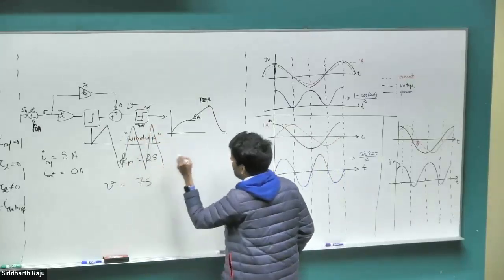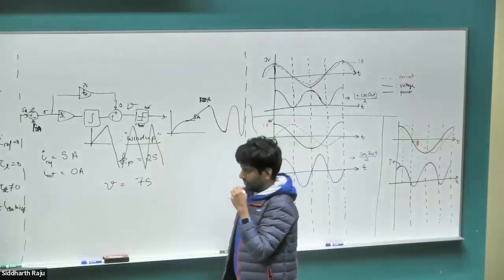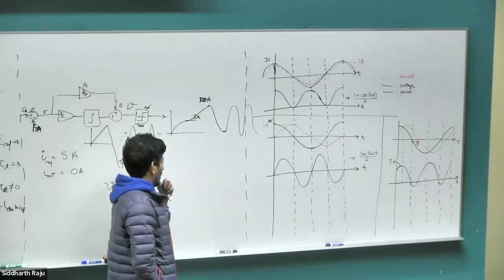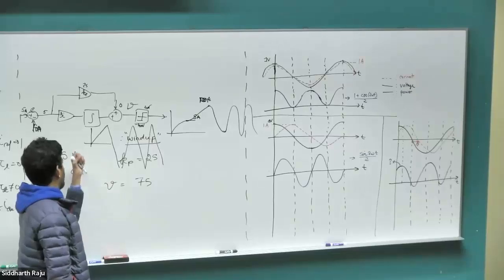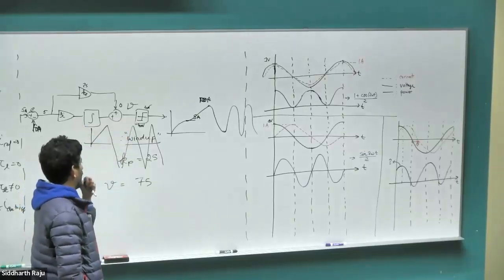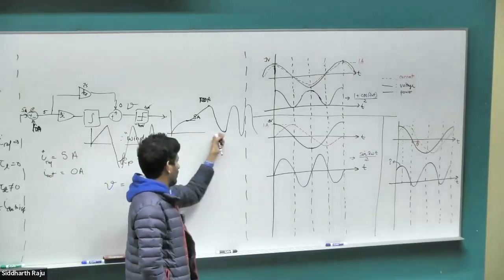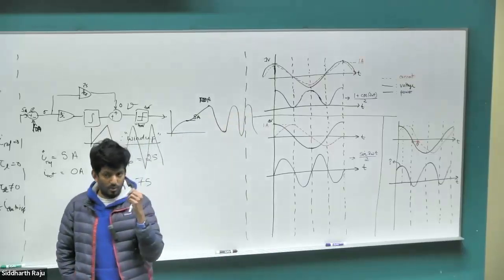It's going to get wound up and down, and your current is going to enter what are called limit cycles. Right, so when you study nonlinear control systems, you look at the theory of how to figure out how the limit cycles occur, but intuitively that's the way it works out. Alright, so you're basically an integrator. If it keeps integrating past what the voltage limit of your converter can do, it is going to end up in this wind-up situation where you're going to end up with these limit cycles where current keeps oscillating, though you should have reached steady state. How do we fix it?